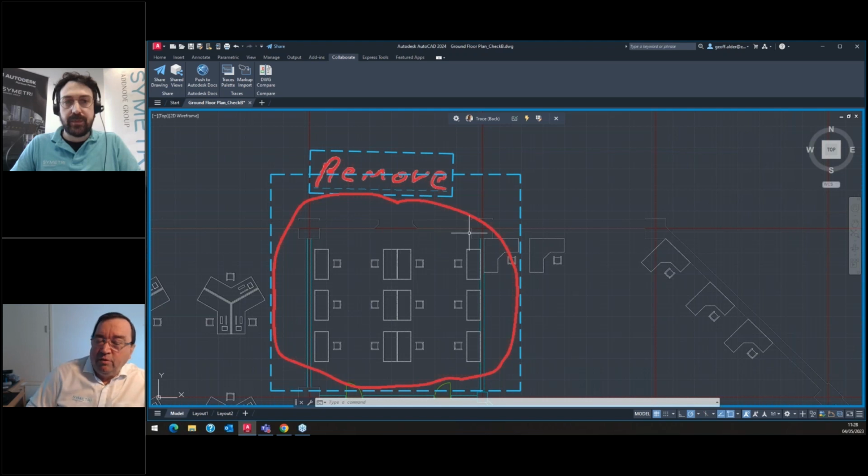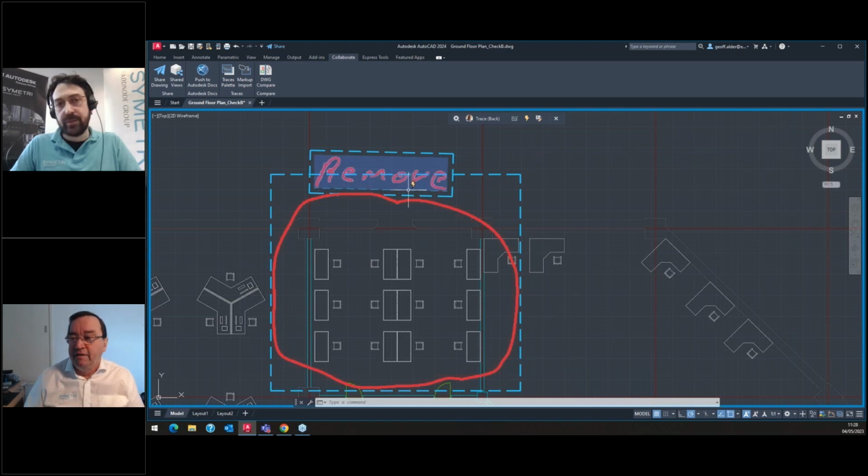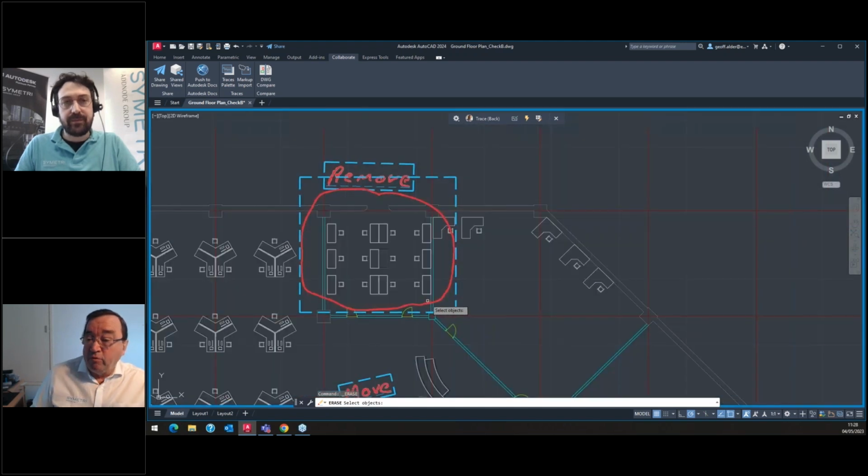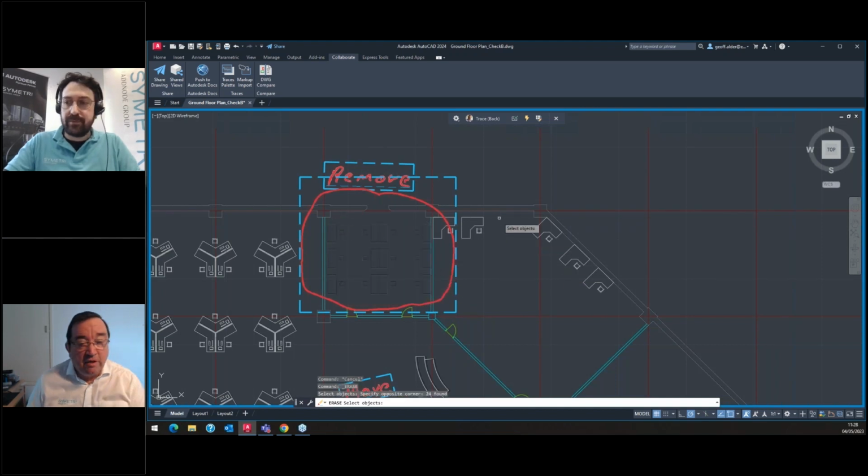And you'll notice on the 2024 now, we actually have that underlined here. And you can see that it's underlined here. And what that means is that if I select the underline here, you can see that on the little tool tap there, it says that it identifies an instruction, which is really nice. So even though I've written the word remove, I can click on that line there and it activates the erase command. So really nice learning there, in that I can just do my remove here. So I can activate the erase command and just completely erase those out the way. So this really works well.